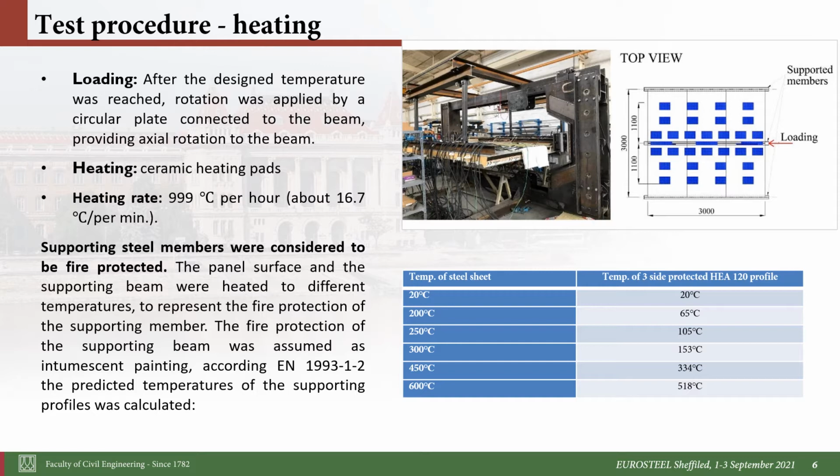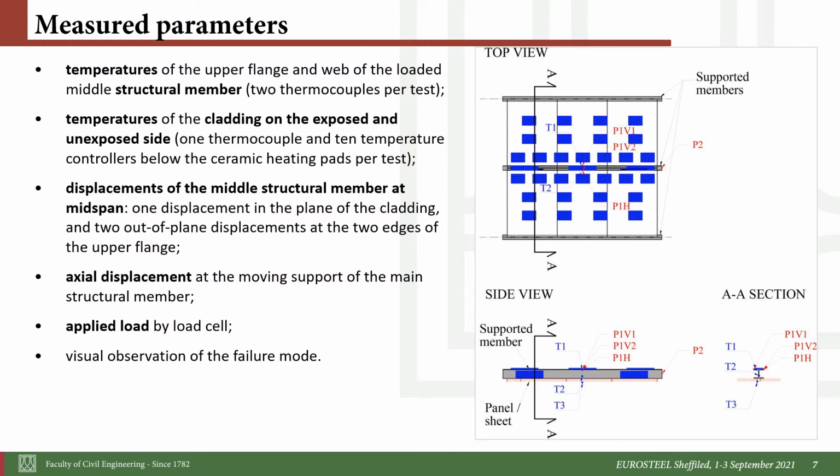You can see some pictures of the test. Here we applied the temperature load by ceramic heating pads. You can see the arrangement of the heating pads here on the right side, and we assume that the member itself was protected against the fire load, so we applied lower temperature there.